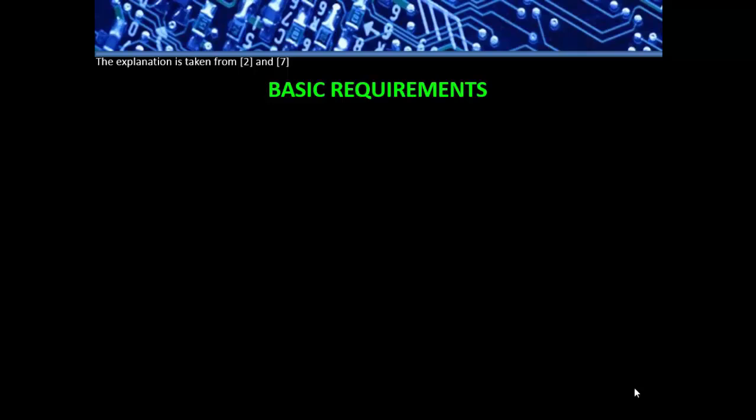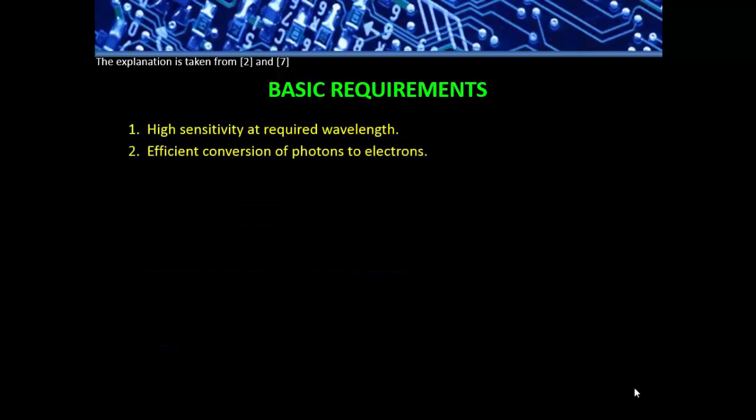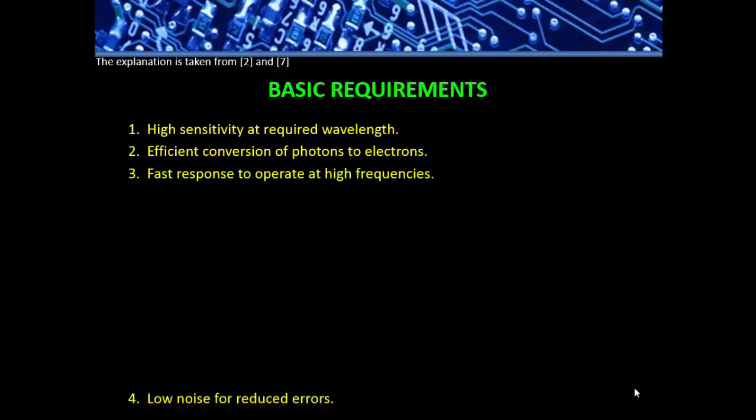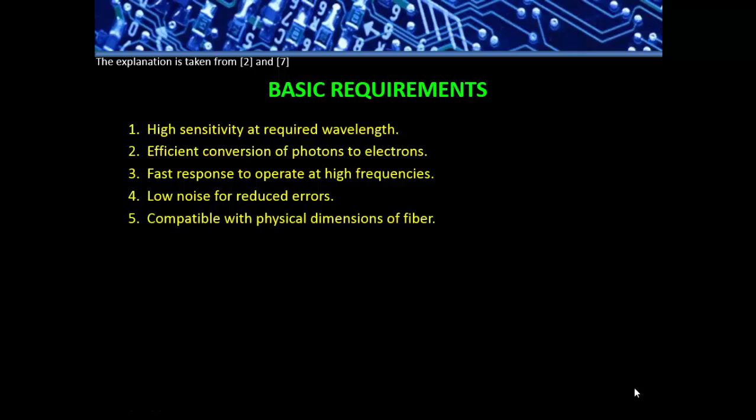The basic requirements of a photodetector are high sensitivity at the required wavelength, efficient conversion of photons to electrons, fast response to operate at high frequencies, low noise for reduced errors, compatibility with the physical dimensions of the fiber, long operating lifetime, and insensitivity to temperature variation.